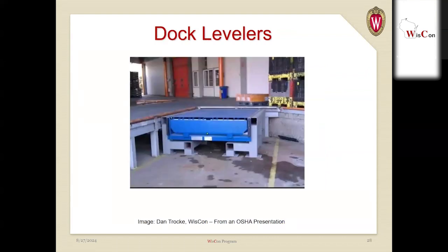Some dock levelers are considered confined spaces, and this throws a lot of people off because when you look at a dock leveler, you don't necessarily think that it's a confined space. But the hazard here tends to be a crushing hazard. So if this dock leveler is not locked out correctly when someone's working on it, they can get crushed by it. And lockout tagout tends to go hand in hand with confined space quite often. So quite often when you see a confined space fatality or injury, frequently there's a lockout tagout issue associated with it too. So you're going to want to keep that in mind.